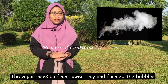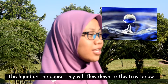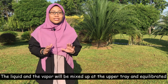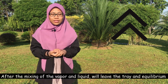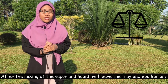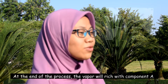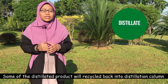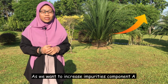The vapor from the lower tray will rise up and form bubbles, and the holes permit the bubbles to go through. The liquid from the upper tray will flow down to the tray below it. The liquid and the vapor will be mixed with each other at the tray and equilibrated. After the mixing, the vapor will leave the tray in equilibrium. At the end of the process, the vapor will be rich with component A, while the liquid will be rich with component B. Some of the distillate product will be recycled back into the distillation column, as we want to increase the purities of component A.